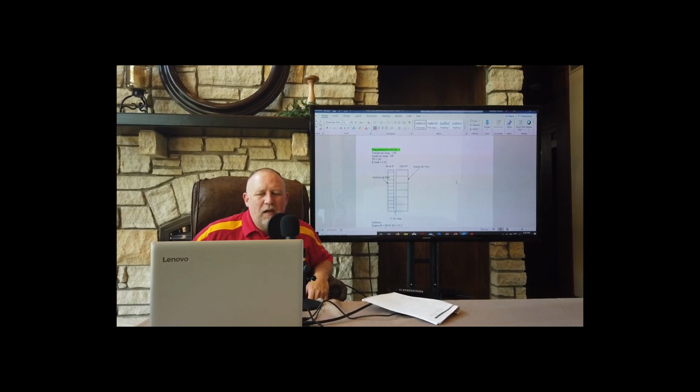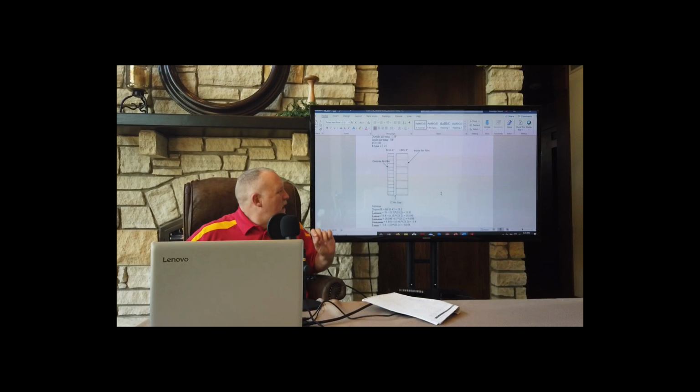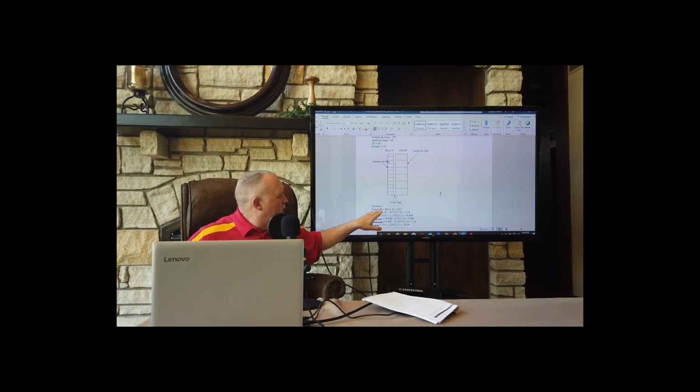This brick and block wall had a total R value of 3.45. So the way to figure out the temperature at each air gap is to first figure out for every one R value, how many degrees does it change? You just divide the total difference in temperature by the total R value for the wall.